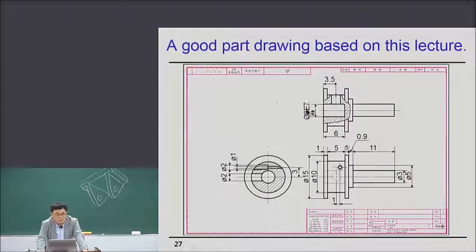Yeah, E7. I was very reluctant to use E7, but since he used E7 in the original drawing, I just copied it. I'm very reluctant to use dimensional tolerance E7, though. Okay, the nice sectional views. So now you can understand very clearly what features are inside the part.